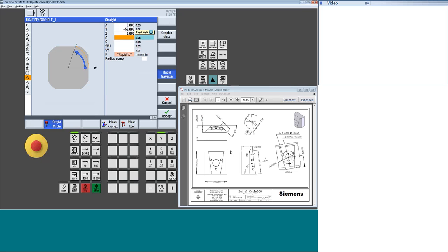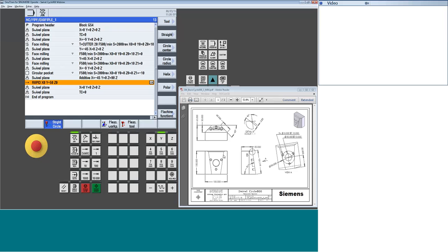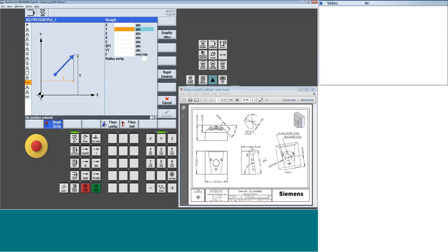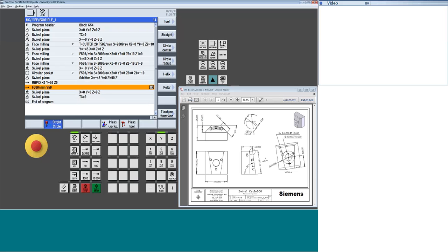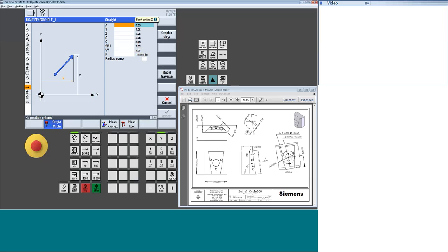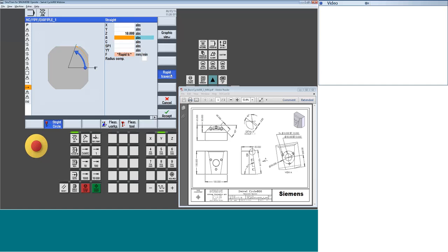Okay. I'm now going to do a straight move in Y to positive 50 mil. And we'll say 500 is fine. Once I get there, maybe I'm going to do a straight move off. Let's say 10 mil in a rapid. All right, we just cleared that chamfer.